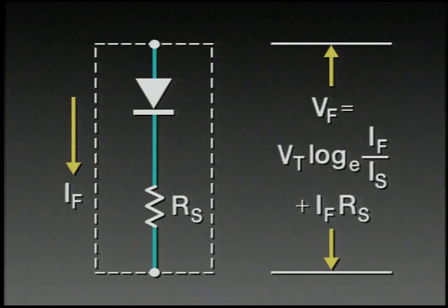That's one of the reasons why we would rarely, if ever, use a diode in a translinear circuit. More likely, we would use a transistor connected as a diode. Before we do that, though, let's consider the consequences of the ohmic resistances surrounding an ideal transistor.